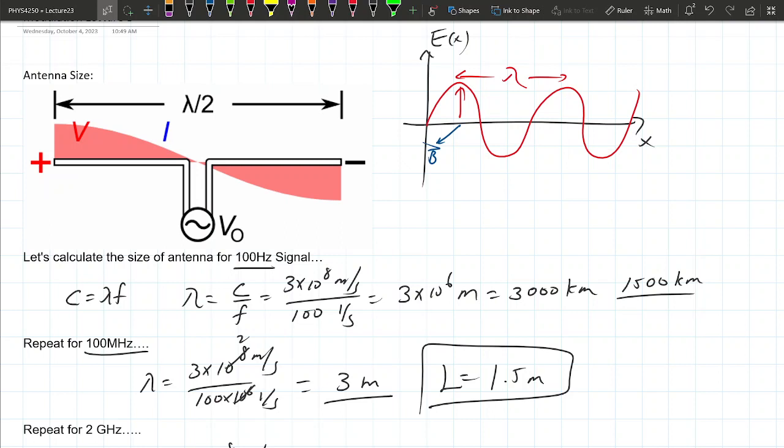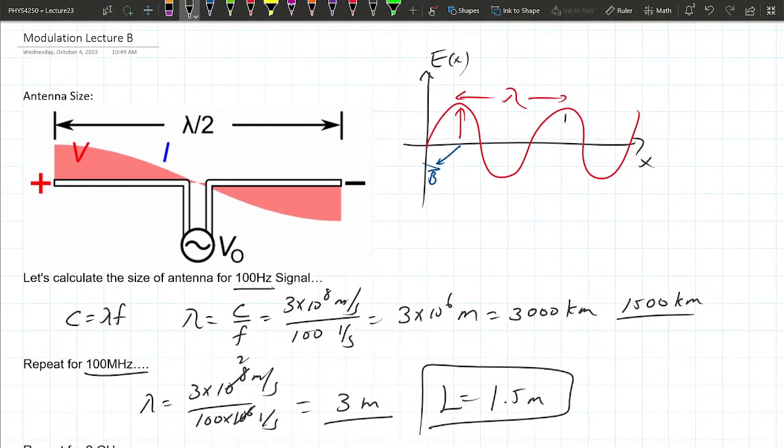Whenever we're setting the function generator, we start with a 5 volts amplitude. That's the amplitude versus peak to peak. That's just a convention thing. When the function generator says amplitude, you're actually setting this value, V peak to peak. The real amplitude in physics is this. Let's say this amplitude is 5 volts. You're setting the peak to peak value to 10 volts in order to get that amplitude of 5. That's just a little silliness with the function generator design.